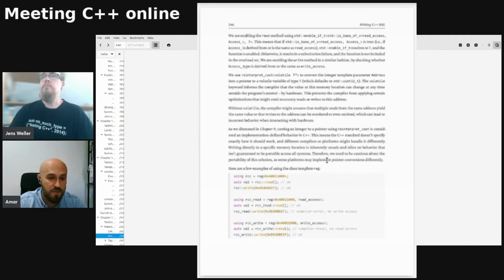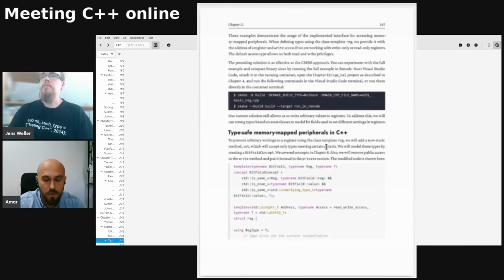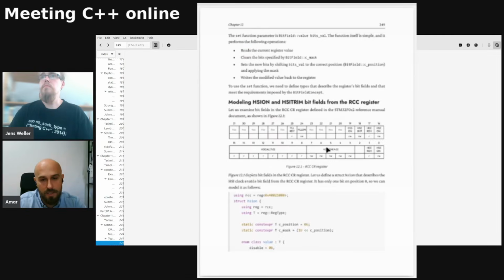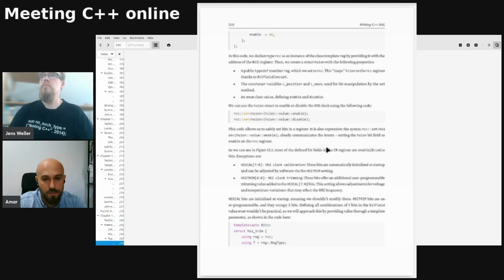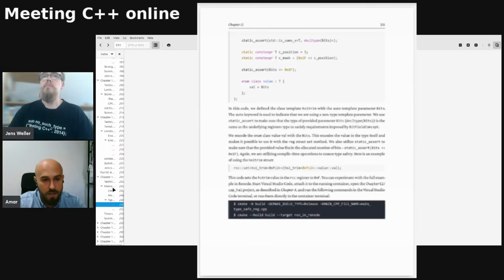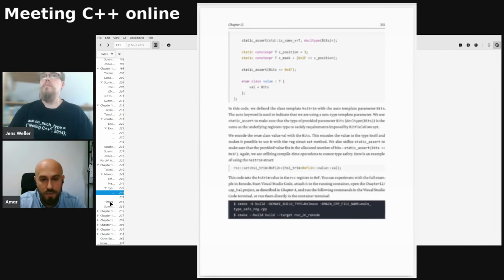So there are registers with some bit fields, and what we want to do is to know exactly at compile time which bit field we are setting up, which value we are writing to it. In C, you can write basically anything at that memory address. Nothing's going to stop you. But with a utility such as this one, we are strengthening that, and we are getting those compile time checks, which allow us to write only valid values in a bit field, right? And we don't pay any price in terms of additional binary size or additional computations at runtime, as everything is being done at compile time.